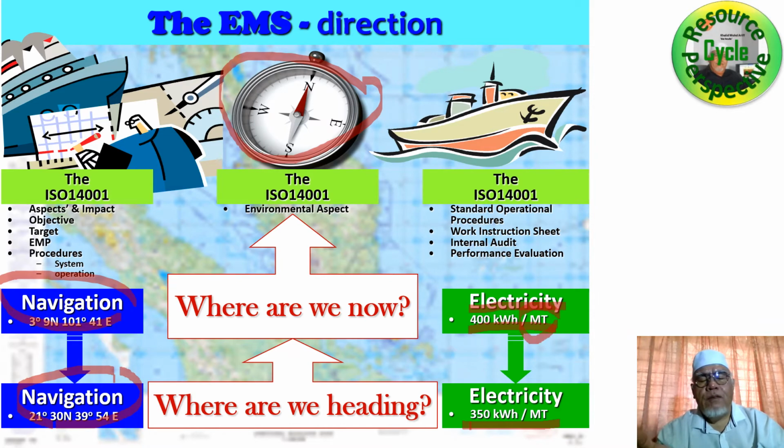We are able to achieve 280 kilowatt hour per metric ton, but we lift it up to ensure that the particular target is not so much pain to achieve. It is about nurturing operational personnel who handle all these machines that use a lot of electrical energy. After a few rounds of brainstorming, we come up with 350 kilowatt hour per metric ton.